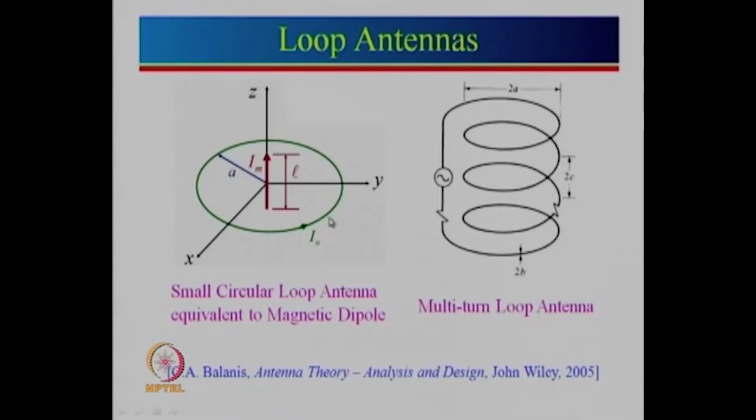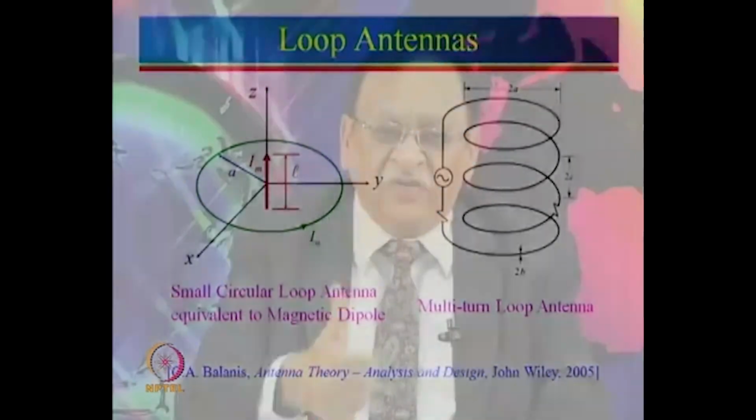See, when we were looking at a dipole antenna, so we had a vertical dipole antenna, and where was the magnetic field? Magnetic field is around the dipole. So, if this is the dipole antenna, magnetic field will be like this here. So, that is what is known as omnidirectional, and then the E field is like this, which was making a figure of 8. So, that is a directional antenna.